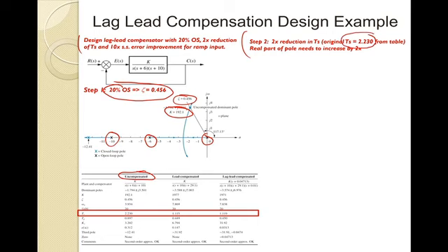if we want to reduce that by a factor of 2, then the real part of the pole right here needs to increase by a factor of 2, right? That relationship here for the settling time is that real part along that damping line. So let's just draw that out, okay? Along this damping line, what we need to do is have this still on that damping line, but that real part has to increase by a factor of 2. So our dominant pole will basically go along that as shown.